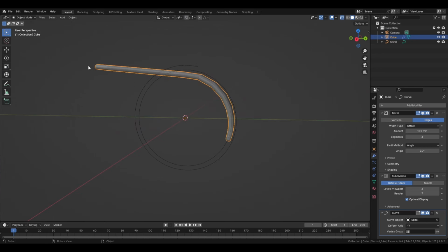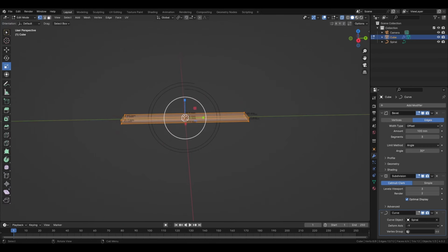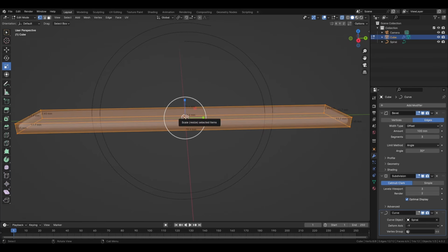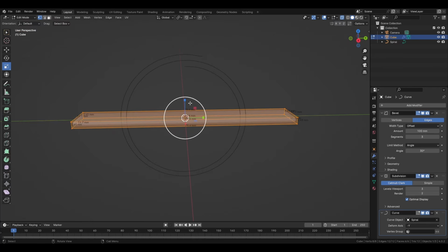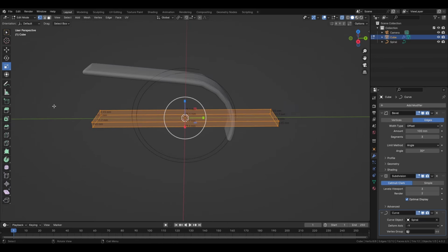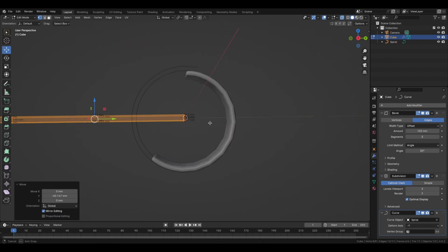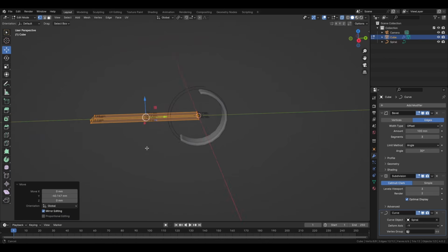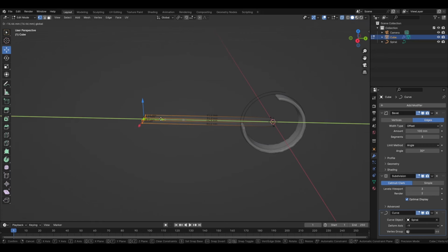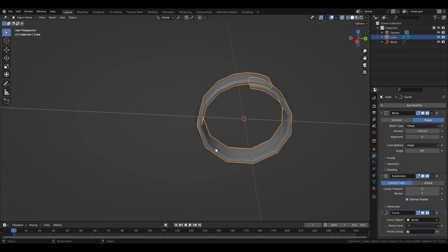And also you see it starts here and finishes here, and this is because you need to put one end of the mesh to the central point of the geometry. So I never know which one it is also, but actually press this to see what you're doing. Select all the thing of your mesh, and then you can move it right here. And actually we need something much longer. Let's do this here, and you see we already have the base shape.